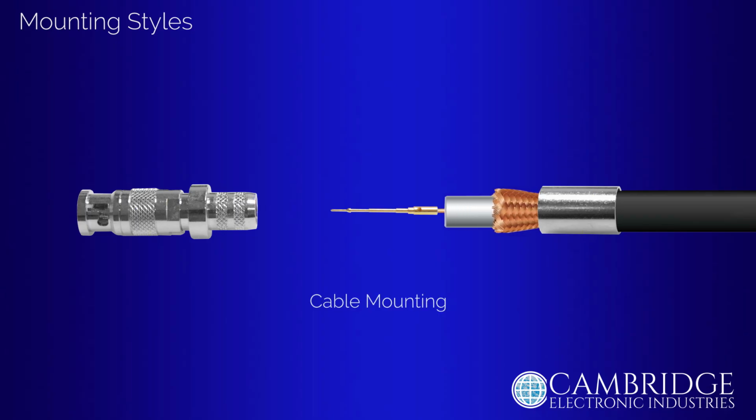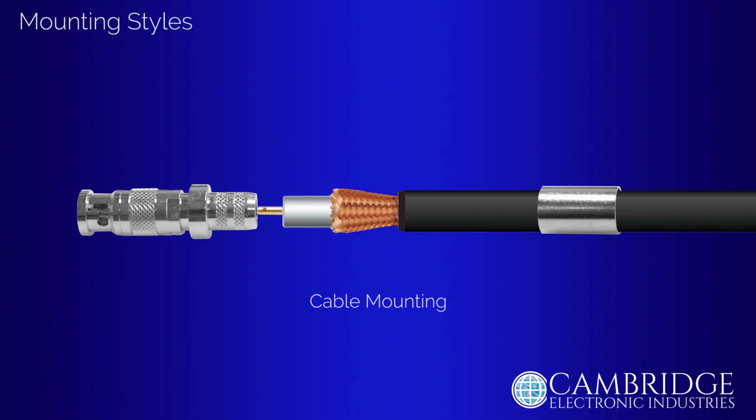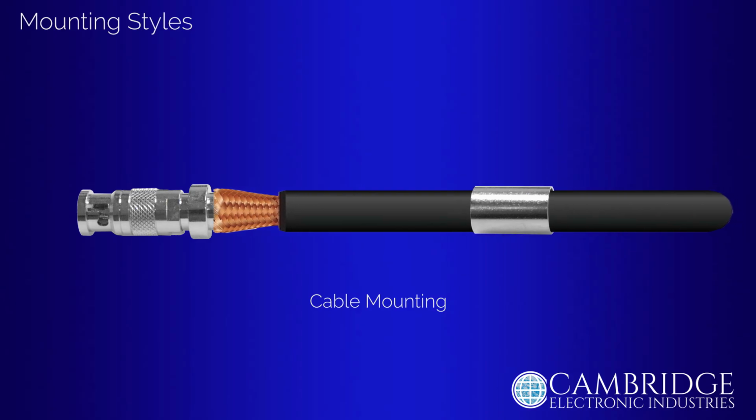The centre conductor is either crimped or soldered to the connector's centre pin. The dielectric fits into the connector's body to maintain impedance matching. The outer braid and jacket are folded back and captured over the back of the connector body, and then a ferrule or metal sleeve is slid over and crimped to provide mechanical strength, shielding continuity, and strain relief.